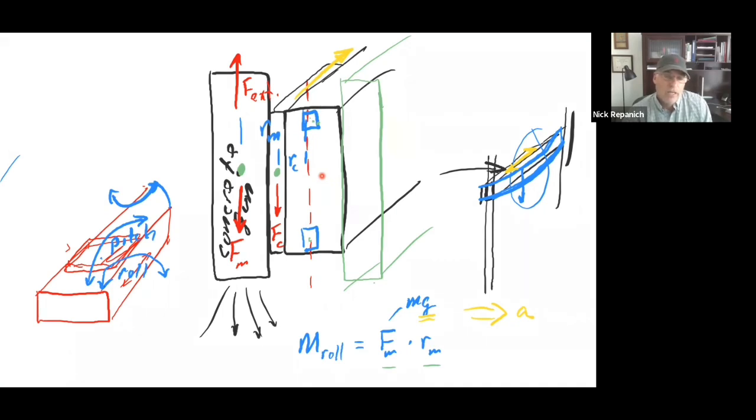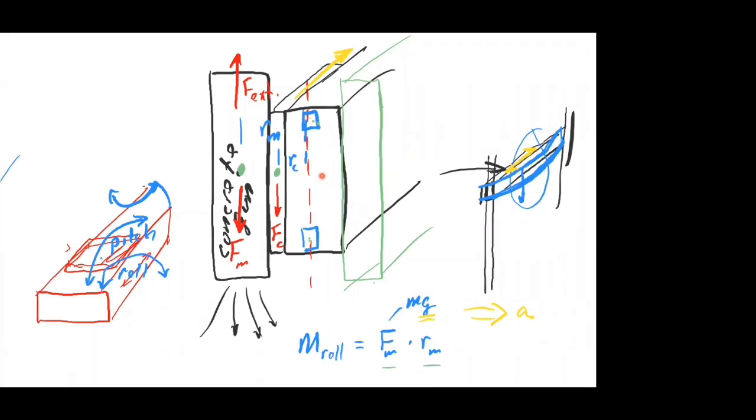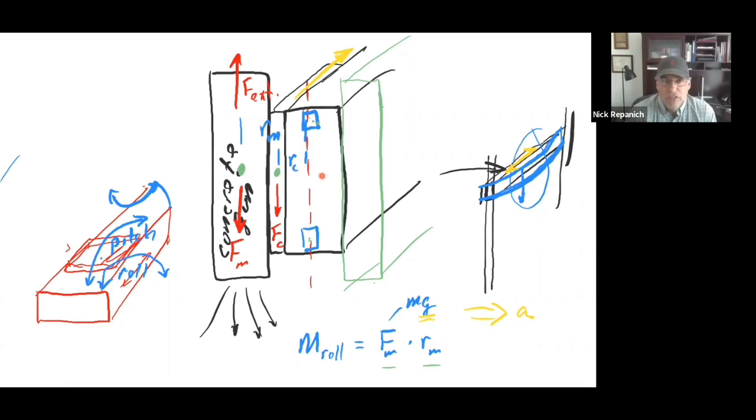And again, when you're designing, there's some amount of engineering, some amount of estimation, and some amount of ignoring the minutia. What I'm really trying to do is not a complete exhaustive calculation. It's to pick the biggest ones and make sure you're checking those. Generally, if you've got a bearing that can handle the biggest one or two moments or forces, it's going to handle the minutia ones too, so you really don't need to deal with them. Some of that's judgment and experience.